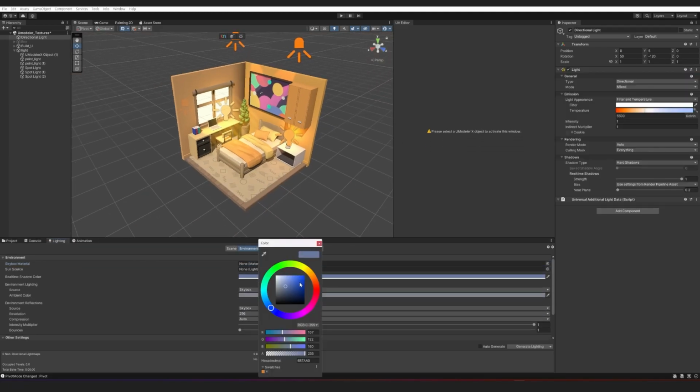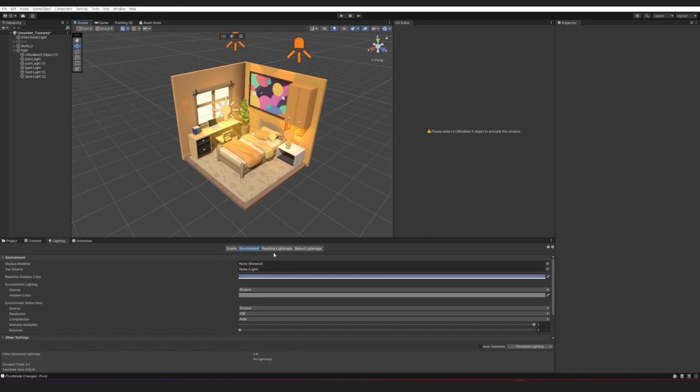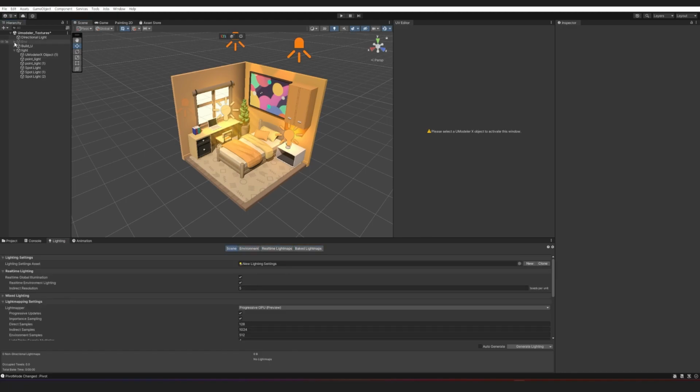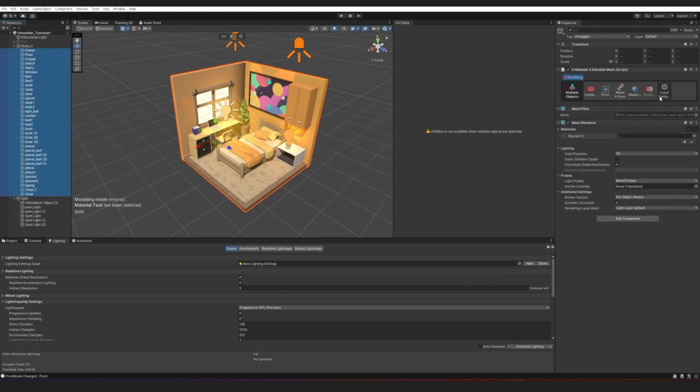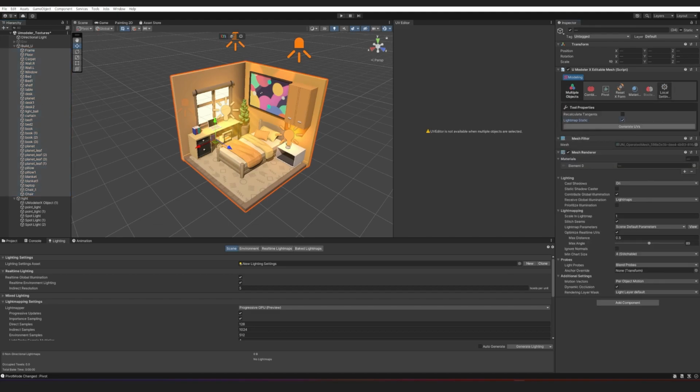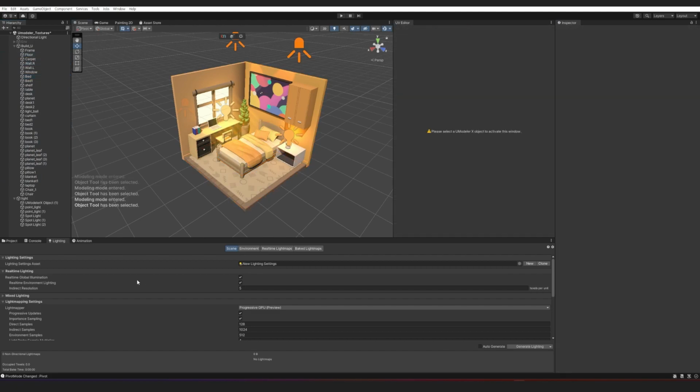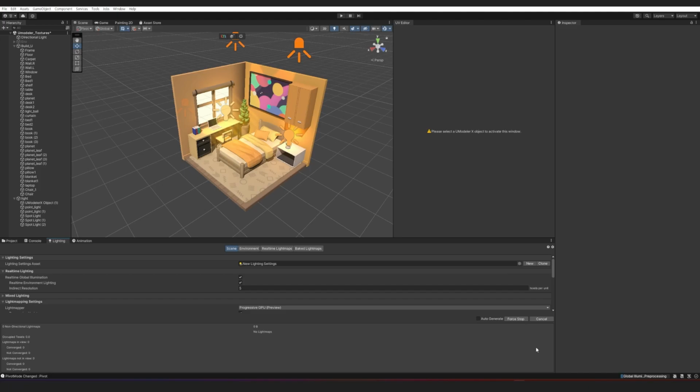Select all objects created with UModeler X for light baking. In the Settings window on the right, check the box to activate Static for all objects, then click the Generate UVs button. Once the settings are complete, press the Light Bake button to execute the light bake.